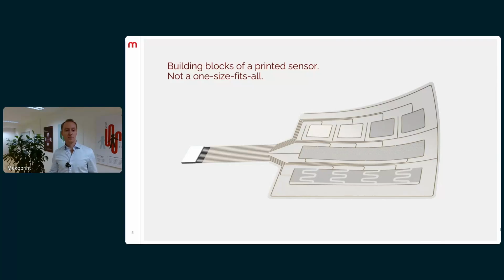There are many different options and materials available, so we don't have a one-size-fits-all solution. It will, of course, depend on the functionality. Like it's a different solution for a touch sensor, a capacitive touch sensor for white goods that's fixed once mounted, compared to a resistive healthcare sensor that's wearable and needs to be stretchable. So requirements for flexibility and stretchability is one of the things that needs to be considered.